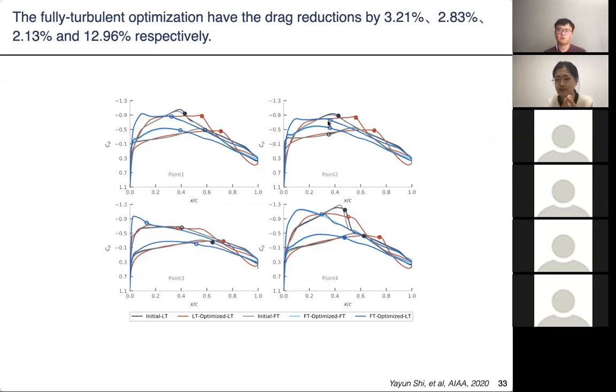For the three-dimensional case, it is very complicated. It needs to balance the friction drag and shock wave induced drag, and for the shape optimization, it also needs to balance the conflicting of the two instabilities, both the Tollmien-Schlichting instability and the cross flow instability, because the favorable pressure gradient is harmful for the cross flow, but it can suppress the Tollmien-Schlichting instability. I see.